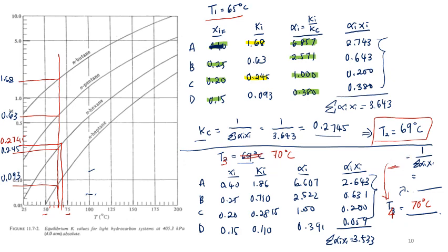Alright, so let's say we want to calculate the vapor composition in equilibrium with the liquid product. So you should refer back to the steps in the previous slide just now. Wait until I finish rubbing this off, just like what we have in class. You just normally wait while I erase something. Okay, so yi is equal to alpha I xi divided by the summation of alpha I xi. So from here, you can calculate what is yi.